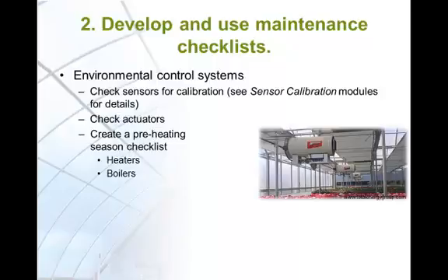The burner manifold and nozzles should be brushed with a bristle brush and cleaned with compressed air. Check gas supply lines for leaks using a soap and water solution. Check spark and pilot for correct operation. Maintain adequate pressure in propane tanks.